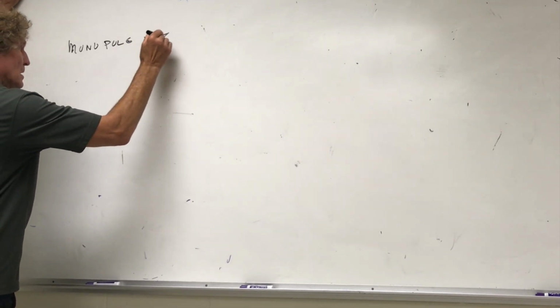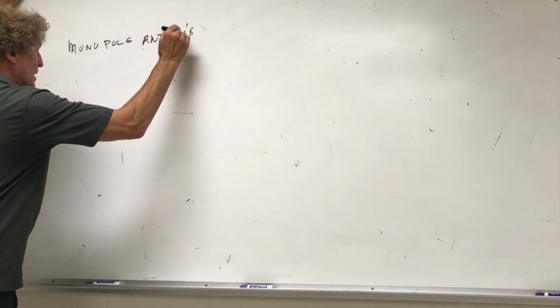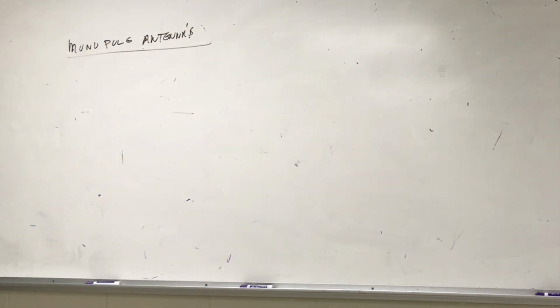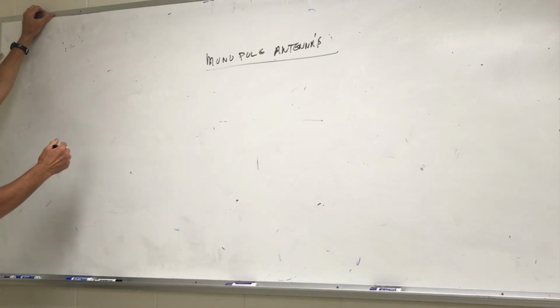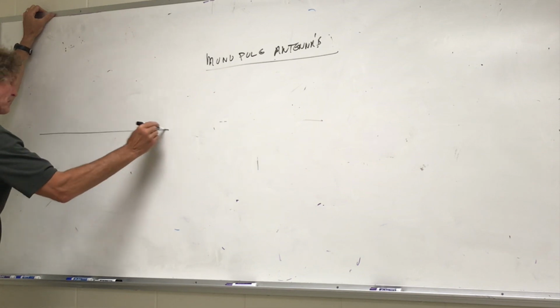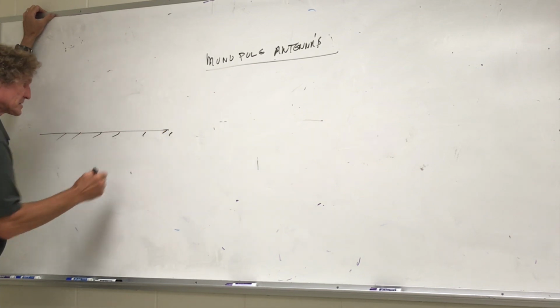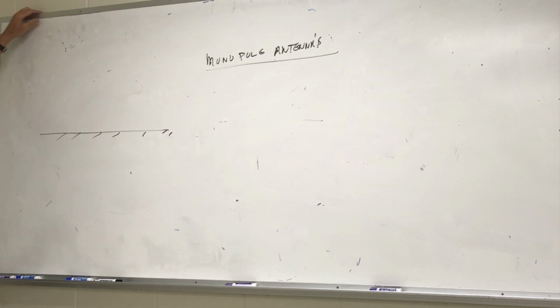All right, so now we're talking about monopole antennas. What that means is we have to talk about current imaging and charge imaging. So I'm going to take a step back before we do this. Monopoles, instead of having 2 lengths of antenna center fed, you only have 1 length. Mono is 1, di is 2, dipole therefore. So if we have a perfect conducting ground plane as such, this is called charge imaging.